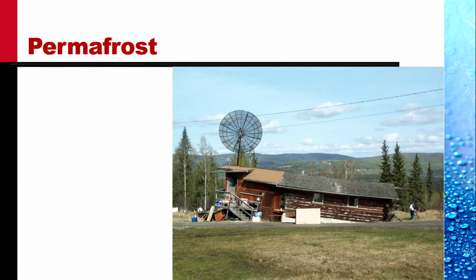It gets hotter and it thaws, and it can no longer support structures. So foundations of the building must be dug below the level to which the effect of the summer thaw penetrates. The layer beyond which the soil does not thaw is called permafrost. So buildings must be anchored in the permafrost.